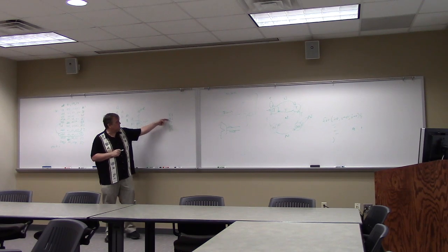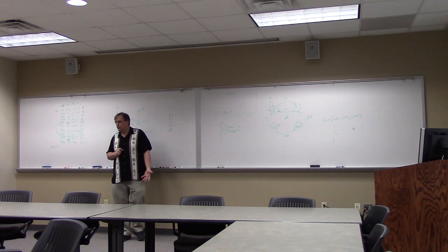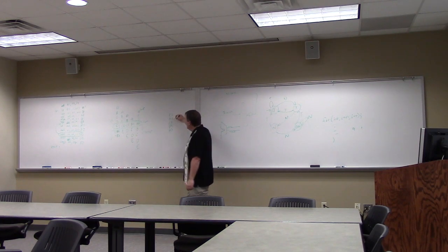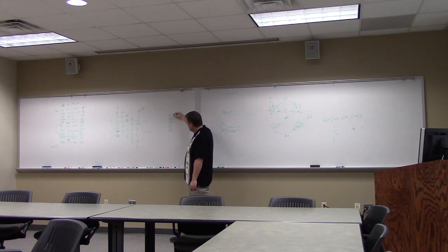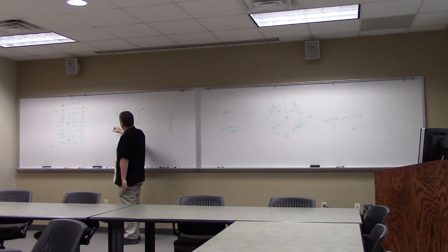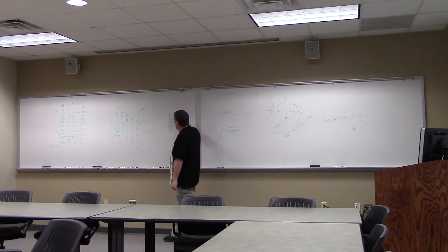No, because E1 fetches before D2 gets its stuff. It's always going to do it, so this one will get its values before that one gets its values, and this one changes values after it gets its values. So there's no way this one can change values before that one can finish. So this is completely safe. There is no way for this D2 to mess up that E1. Totally safe.